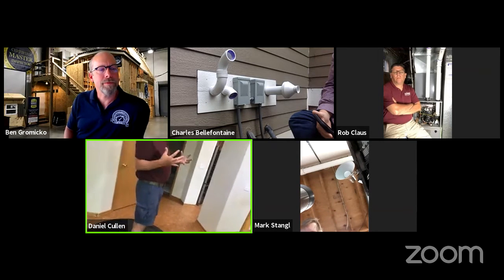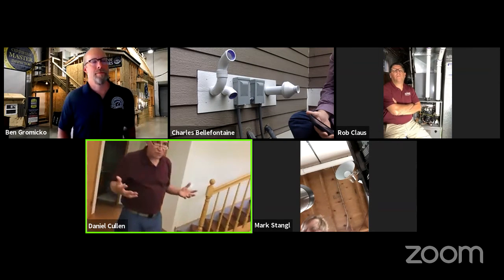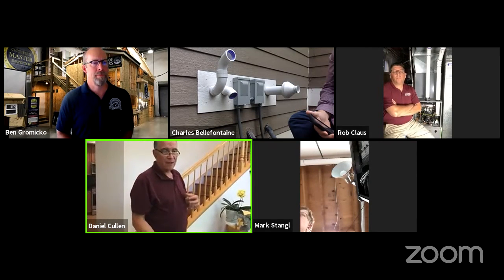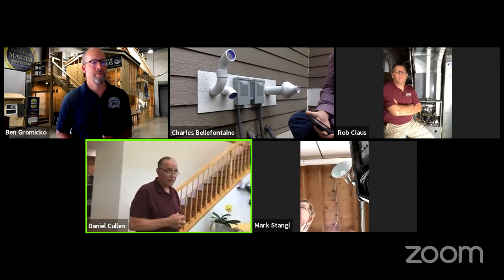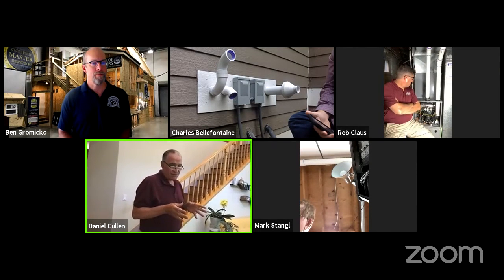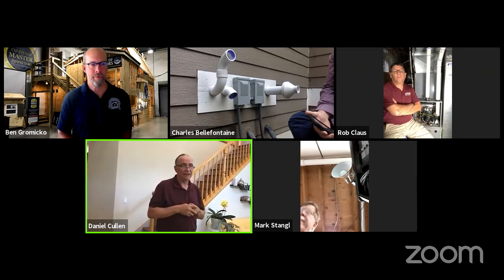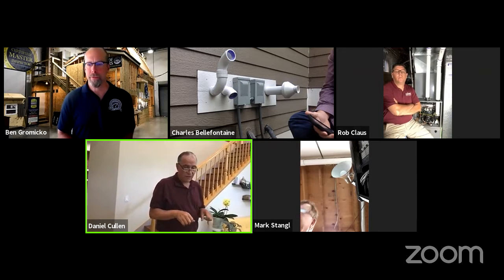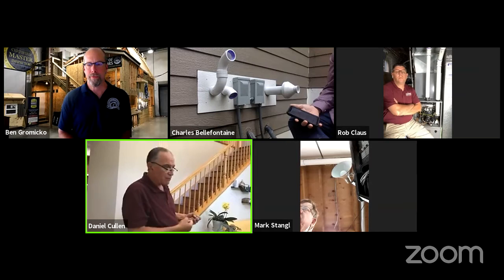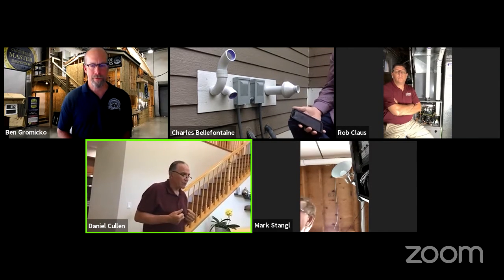As I said, we don't have enough return air on this lower level, and that's something that I absolutely point out to my clients. Just this morning, I had an inspection of a 3-level townhome with inadequate low return air. They're going to be miserable there in the wintertime. It's not going to be warm enough in that lower level. And in many of these 2, 3, and 4-level townhomes, that lower level isn't tenable in the wintertime because we're on a slab and because cold air is dense and sinks, and we don't have the capacity to grab that cold air off the floor, send it back to the unit, and regurgitate it, so to speak.